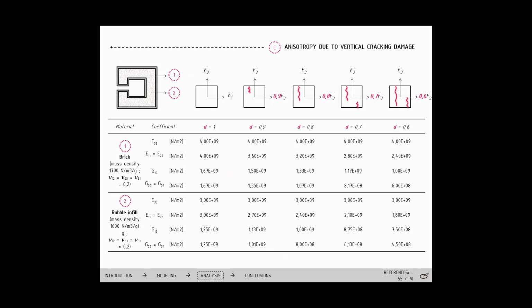Okay, so here you can see the properties of the materials with the damage parameters. To define these materials in FX+, we simply created two different materials for each damage parameter. For the damage parameter equal to 1, which is the isotropic condition, we have already created the material property. So we need to create a total of 8 new material properties. We use this table to fill in the property values.